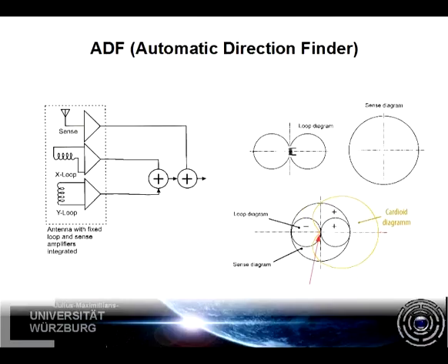The dent in the pattern is the point of minimum reception strength and gives the best margins to identify the direction from which the NDB signal is coming from. Even the oldest ADF receivers were able to get a fix on the station with an error of less than 3 degrees this way.